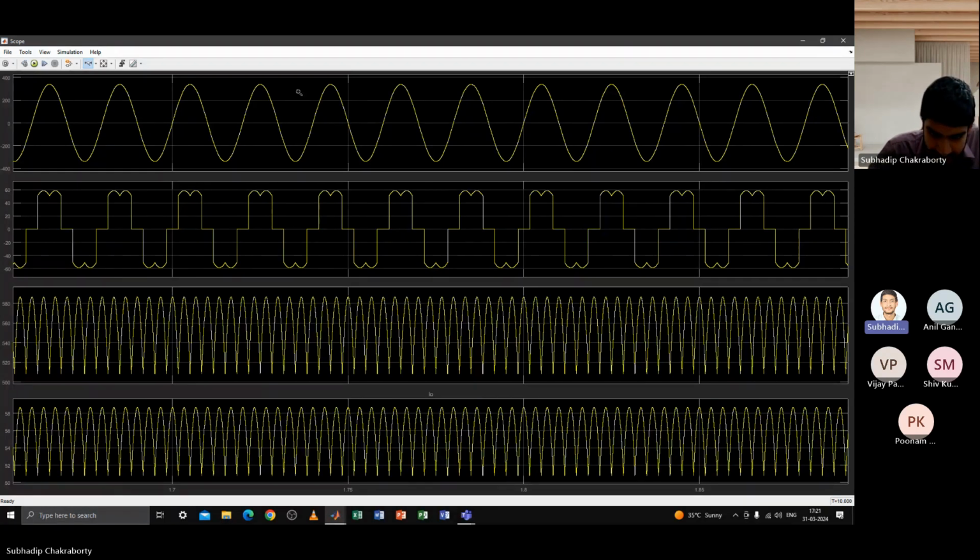For example, if I give you a problem stating that you have to design some power filters, I should also give you the targets for what you should design the filter. For example, I tell you my load current has so many harmonics, but you design the filter to only compensate the dominant harmonics. My load is fully distorted, containing maximum fifth harmonics, so I tell you to design a cheap filter which has only fifth harmonic compensation, no other elements. You will design such that your filter provides a low impedance path to the fifth harmonic. Now, if I tell you to design for fifth and other higher order harmonics, you design a fifth sub-branch and a high pass filter branch.